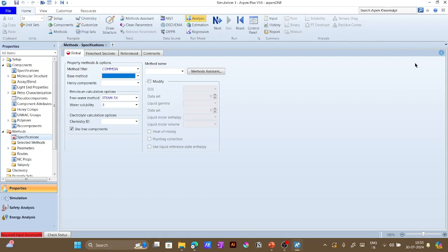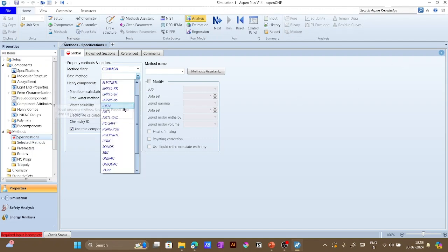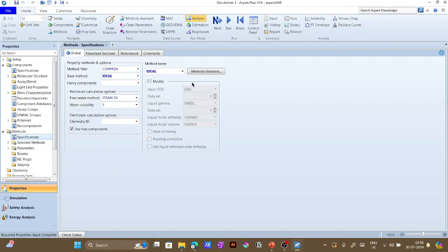So my initial assessment, specifically for those who are looking into this subject or want to work in this Aspen Plus simulation direction more thoroughly, is to dwell into these various properties and understand them. For right now we will just select an ideal model, since we just want to understand the basic interface. Now with the ideal model, when we have entered this value, you can see this required input is complete, so this icon has changed. Initially it was half-filled red, right? So right now it has changed.